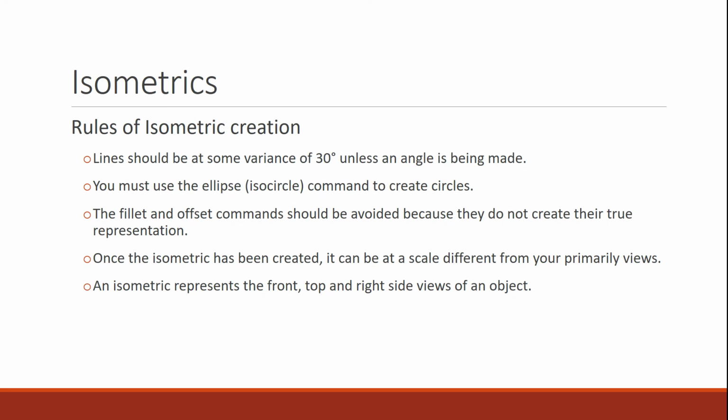Okay. When you create an isometric view, it does not have to be to scale. Typically, your isometric view is nothing more than a reference. Now, the only reason I say that it can be to scale is if you're going to put dimensions on it. It makes your life so much easier if you create it at scale, if you plan on dimensioning it. But for what we need in this class, it can be any size that you want it to be. Okay, so it's nothing more than a reference.